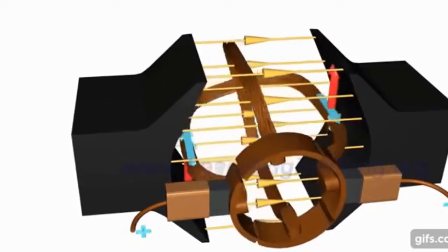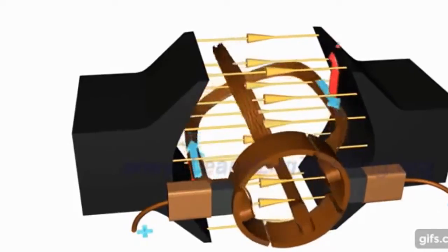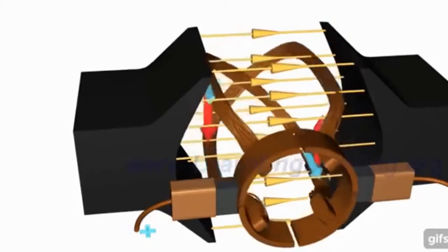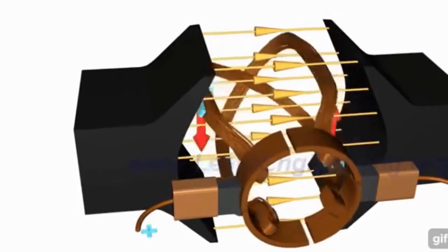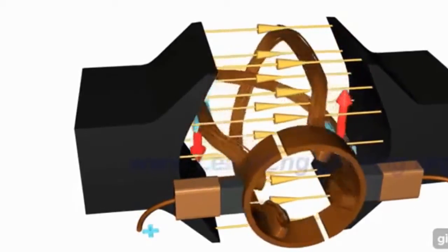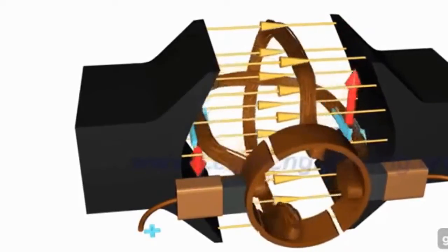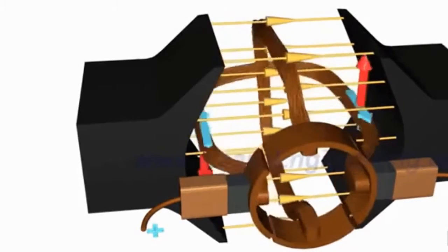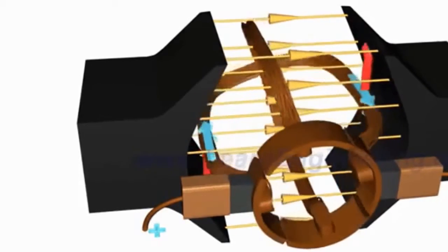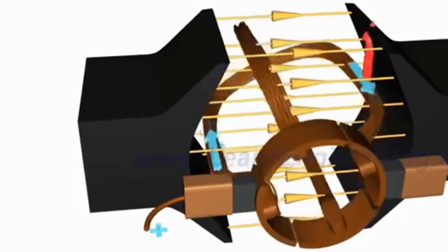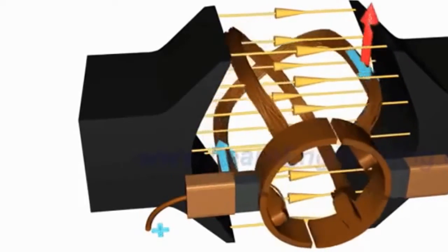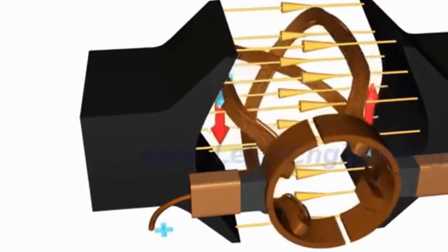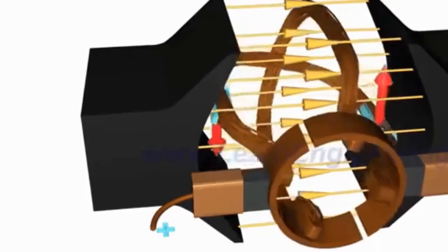Here, when you apply current to a motor, one of the electromagnets starts up and it gets attracted or repelled by the magnets. Now, due to this movement, the motor rotates a little bit and then the electromagnet turns off and another electromagnet that is next to it starts up, and it is at such a distance that it again gets repelled or attracted by the magnet, and this process continues. That gives you a continuous rotation in a DC motor.